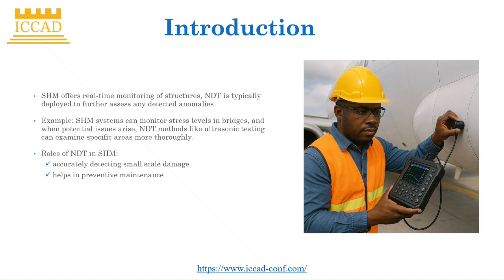Structural health monitoring offers real-time monitoring of structures. Non-destructive testing is typically deployed to further assess any detected anomalies. For example, structural health monitoring systems can monitor stress levels in bridges, and when potential issues arise, non-destructive testing methods like ultrasonic testing can examine specific areas more thoroughly.